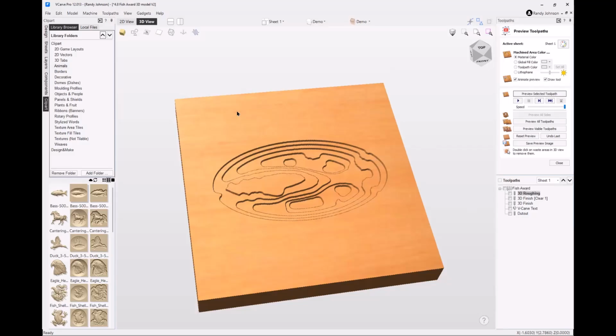For roughing, like you see in the photo right here in the presentation, I will sometimes use a straight bit for this, a straight flute, a single or double flute, 1/2 inch, 3/8, 1/4 inch. I will use that for that. But for most of my fine cutting, I use an up spiral, either single or double flute.